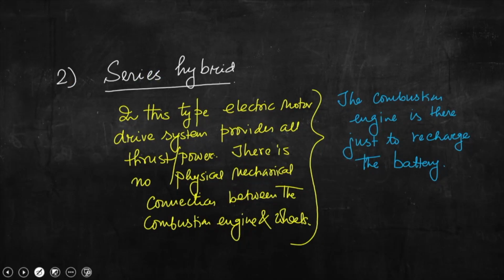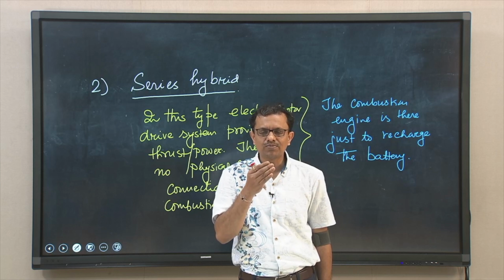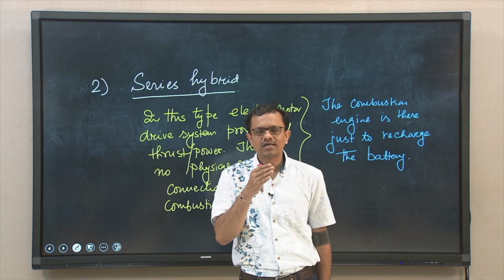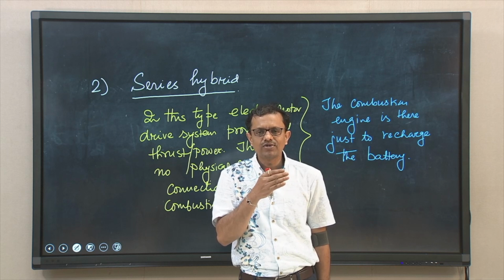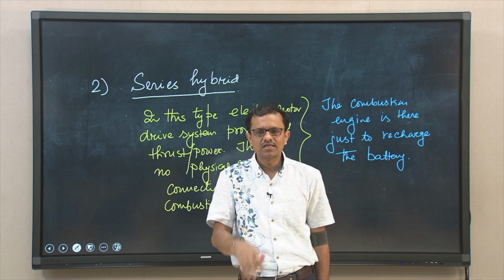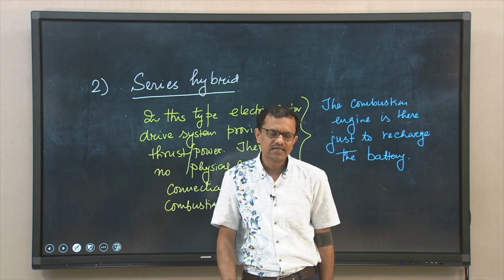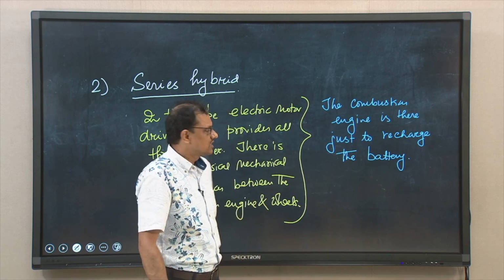That means, since the combustion engine has no direct role as such, it will be there to develop power to charge the batteries, but essentially the wheels or engine shaft or crankshaft should be connected to the shaft of the motor. Then what can we have? We can have smoother engine transmission as well as operation, as well as powerful acceleration. So, the engine will run smoothly. So, this is all about series hybrid.